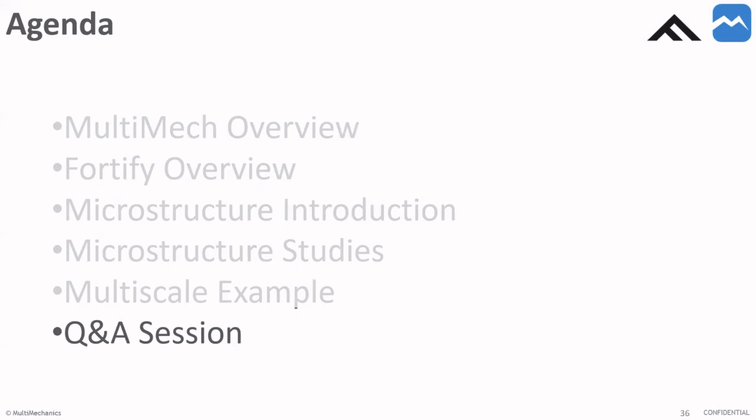And the answer is yes. You can import this in the fiber orientation tensor. Basically, along with principal direction, it also defines the amount of misalignment. So you can have perfect alignment, or misalignment, and everywhere in between.